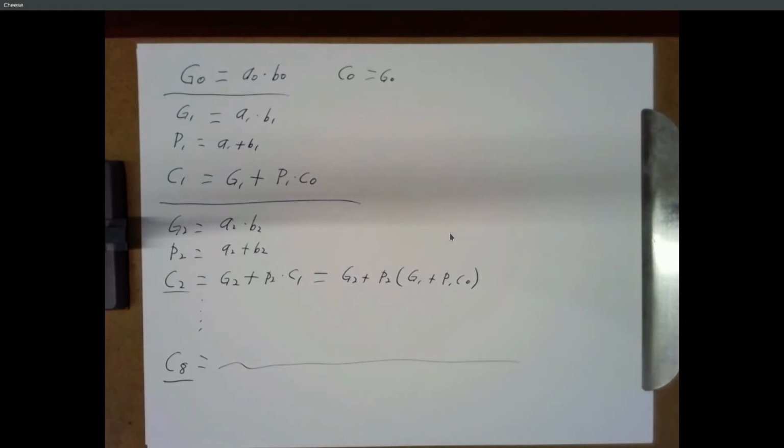As opposed to doing a ripple carry, where it takes you 10 nanoseconds to find the first digit, and then 10 to find the second, and then 10 to find the third, and after 80 nanoseconds you get your final carry out. So this is throwing hardware at the problem. It's making it run quicker, but it takes more resources, more physical stuff. Which also means more power, more space, more heat generation, and so on. But that's a carry look-ahead adder.